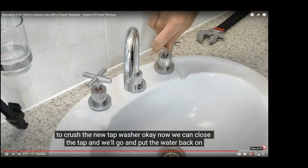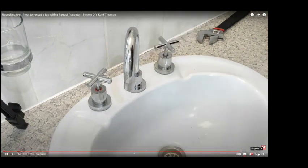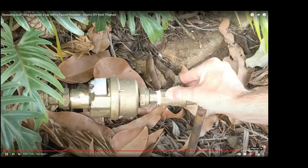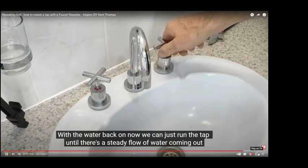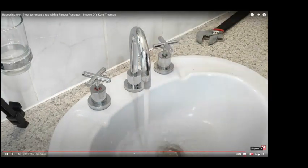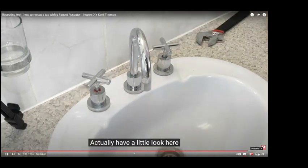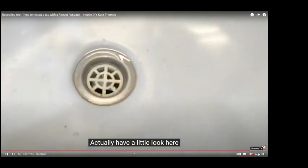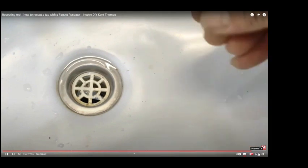The other thing is, if it's really old, especially if it's been leaking internally, it can be really hard to get that chrome cover off. Like he just went in there with that pair of multis. That is something I've done before, is use multis. But sometimes the only way to get it off is to squeeze it so tight it's going to damage the chrome. It's going to dig and bite into it. So if you have spares from old ones, keep a few, because you can save one you're wrecking somewhere else and stick it on and make it look all right.